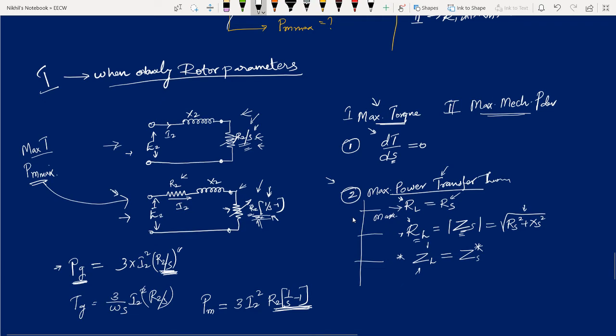So if I want to find out the torque developed in any induction motor, it is equal to, just divide this power equation by omega s, isn't it? Now you see torque is directly proportional to the total resistance component. That means what I'm telling is justified. In order to derive the condition for maximum torque developed, you have to consider R2 by S as the load in your equivalent circuit diagram, and then just proceed.